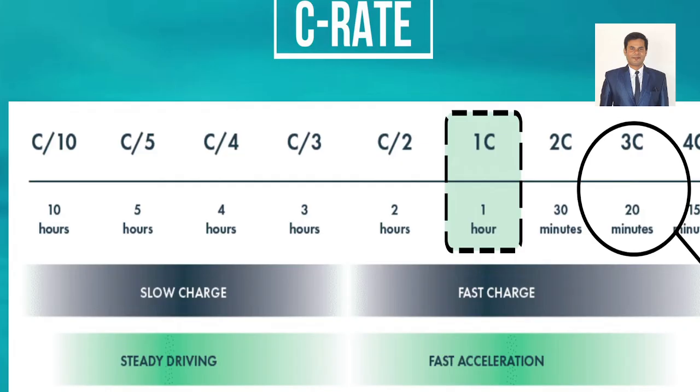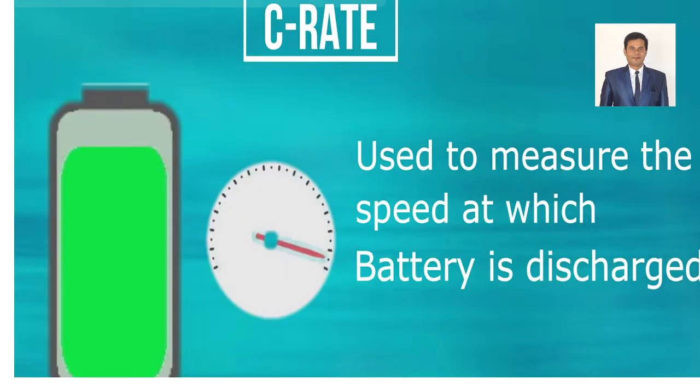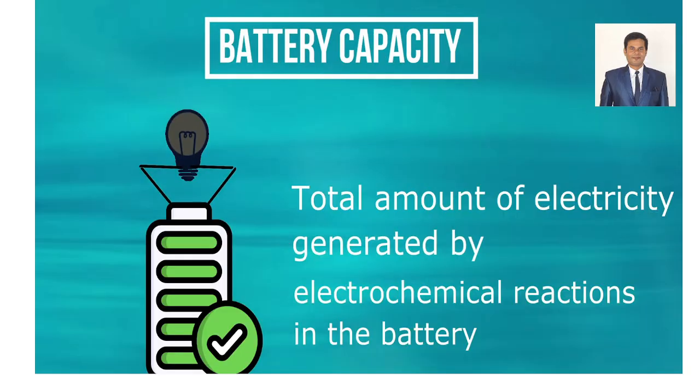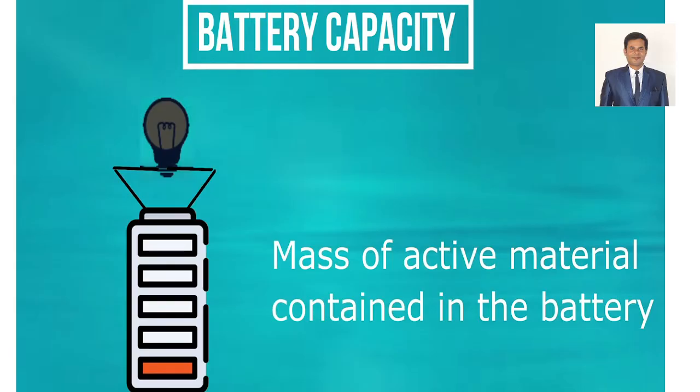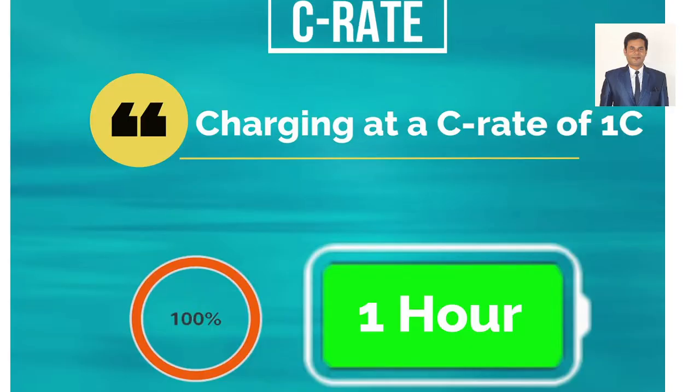During this time you have to focus more on the battery temperature. I've just shown the data from the Excel sheet. We have to monitor the temperature also, because temperature determines the life of the batteries. If the temperature increases in the batteries, degradation will happen very soon, so please focus more on battery life.